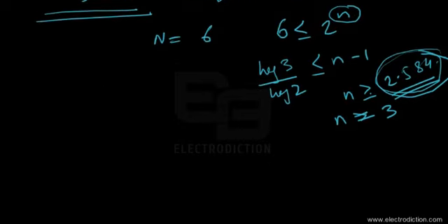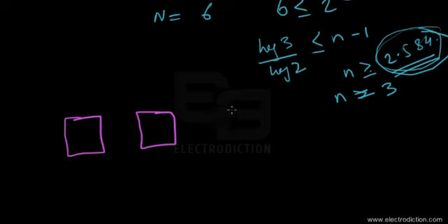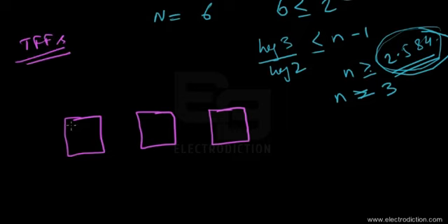So, enter the circuit of a mod 6 counter. Therefore we have, that's too small in size. That's 1, that's 2, and there are 3 flip-flops. Here we're going to utilize T flip-flops to construct the circuit of a mod 6 counter. So this is T1, T2 and T3. These are the T inputs of the T flip-flops.